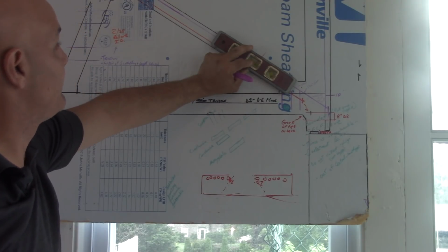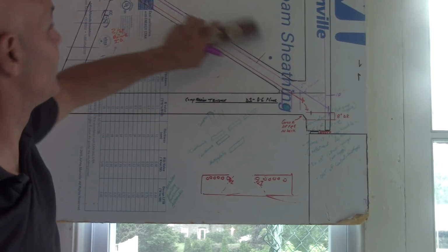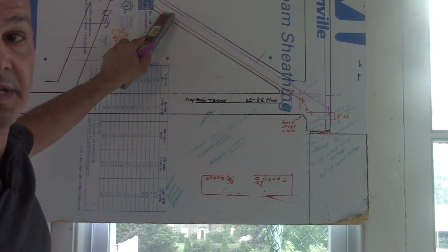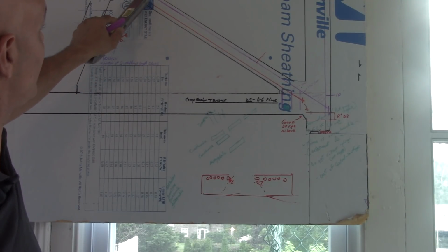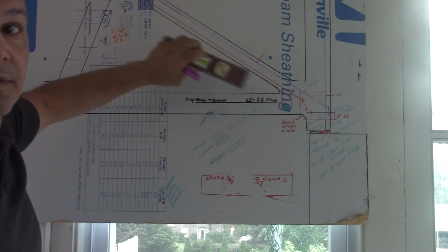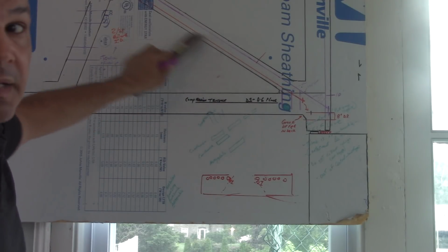To move, that would be to separate it on number 11. Magically, it would lose its forces at that point. And once it separates, it no longer has forces. It's broken. It's in tension at that point, and it doesn't have the capacity to push anymore. So we don't even see buckling in this member.